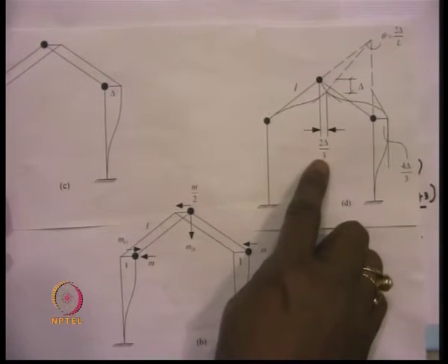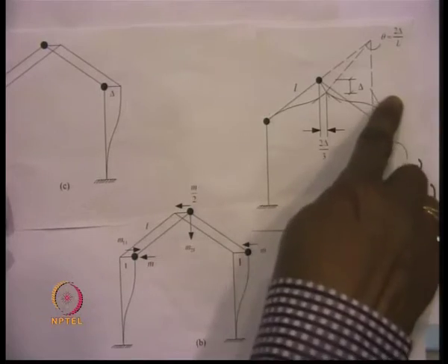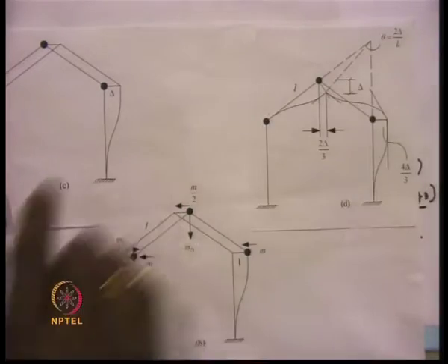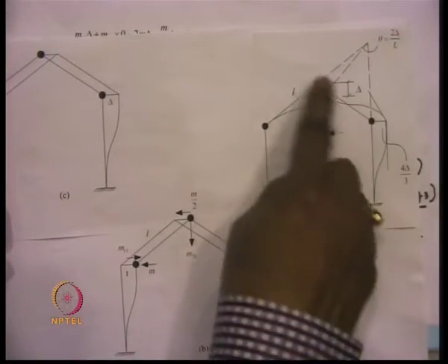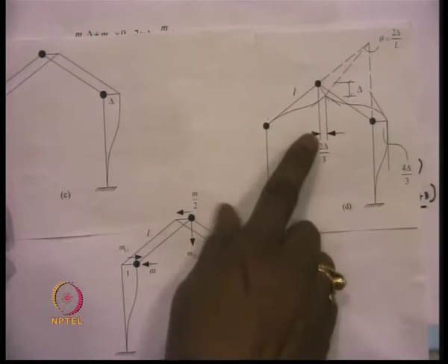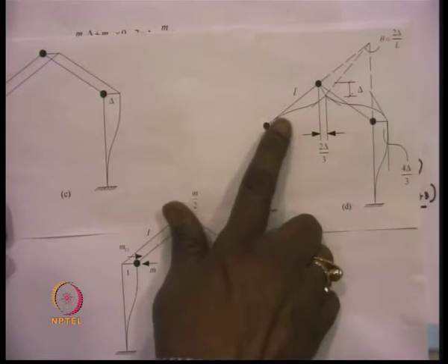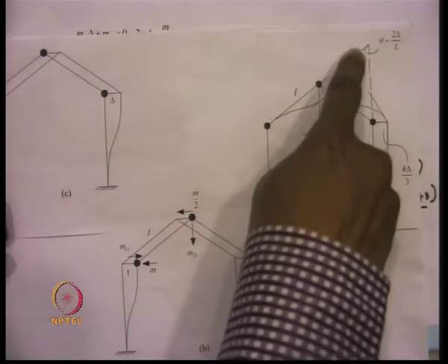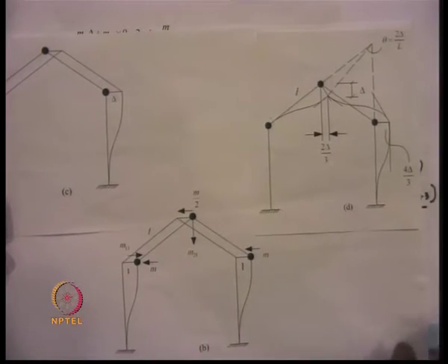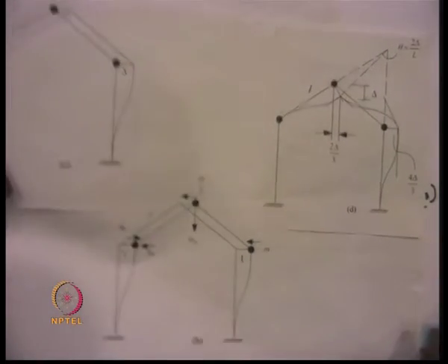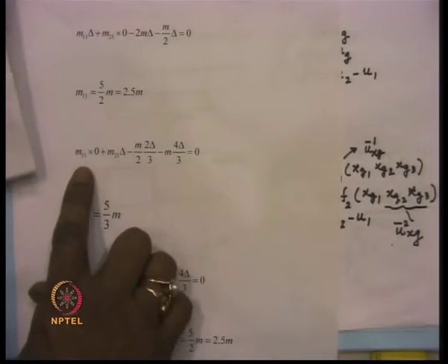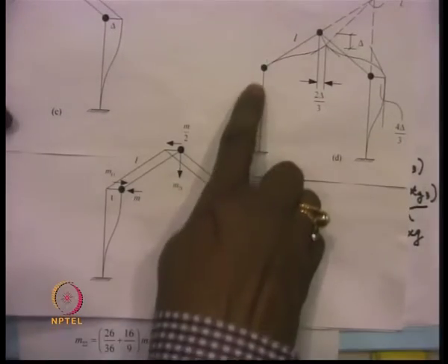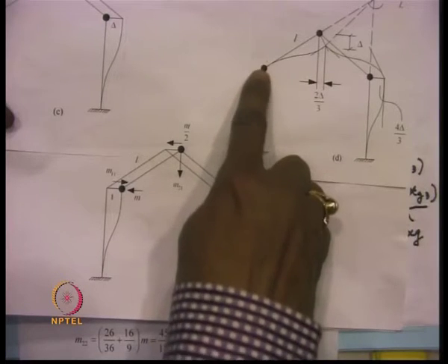So, these are all arising because of the geometry of the movement of this particular pitched portal frame, considering an instantaneous rotation over here. Now, once we get that, then one can write down m11 into 0, because here there is no displacement.